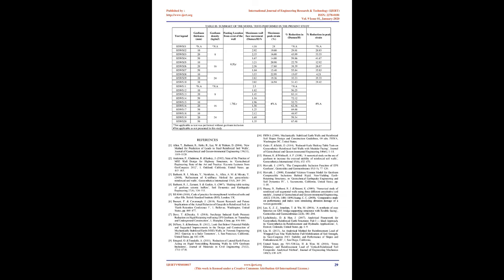When geofoam inclusion is made behind the reinforced zone, peak strains were observed to shift towards the center of the reinforcement layer. The peak strains were observed to reduce significantly with geofoam inclusion. Also, the line of action of the load distribution was found to be extending outward, which indicates a wider load-bearing area and thus lesser peak strains. This is mainly due to the fact that the allowed deformations at both the ends of the reinforced zone distribute the load evenly within the reinforcements, and the strength mobilization at both the ends helps deflect the load distribution line outward.